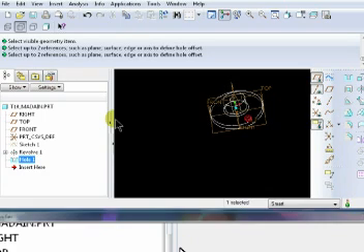Now we need to create a pattern, which happens to be a radial pattern. Now the difference between radial anything and diameter anything is the translation of the dimension. So if you reference an axis, if it's radial, it's going to reference the distance between that object and the axis, which is the radius. And if it's diameter, then it's going to multiply that by 2.